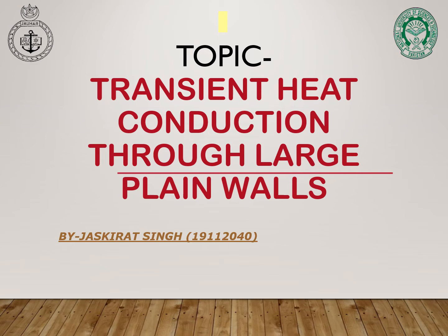Conduction occurs more readily in solids and liquids, where the particles are closer together, than in gases, where the particles are further apart. A medium is required in conduction. Convection is the process of heat transfer by the bulk movement of molecules within a fluid such as gases and liquids. The initial heat transfer between the object and the fluid takes place through conduction, but the bulk heat transfer happens due to the motion of the fluid. A medium is also required in convection.